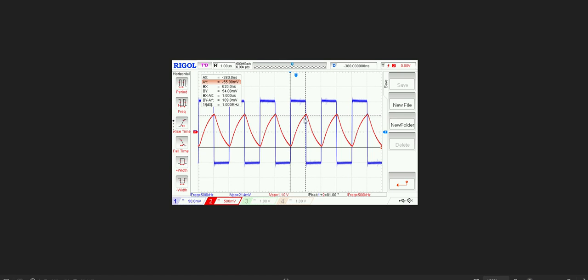You start seeing a little bit of linear distortion. And then once you see linear distortion like this, you're going to measure the value, the amplitude of the signal. So I'm measuring a peak-to-peak value, which is 1.1 volts, which means that I would be getting a slew rate of 0.55 volts per microsecond, because you're taking the amplitude, and what I'm measuring is a peak-to-peak value.